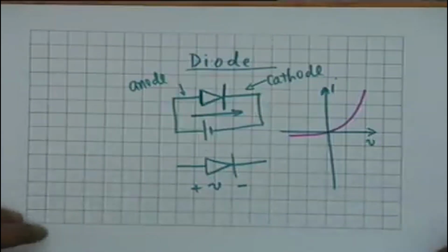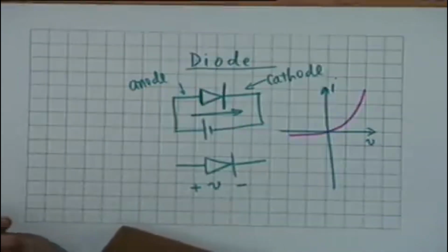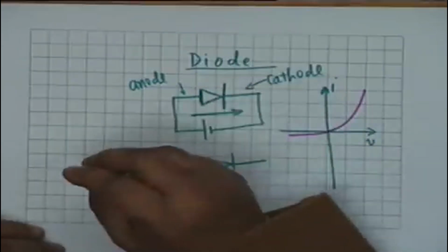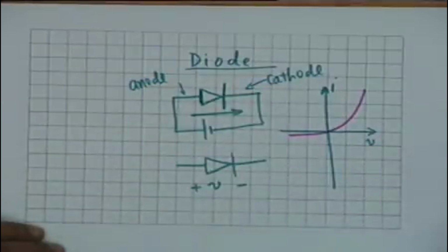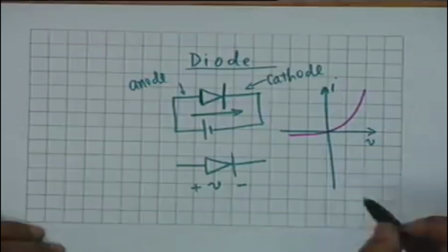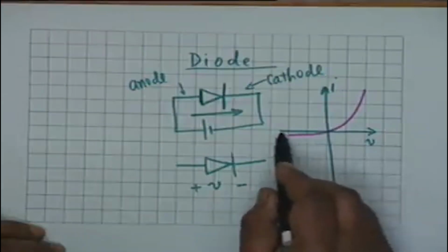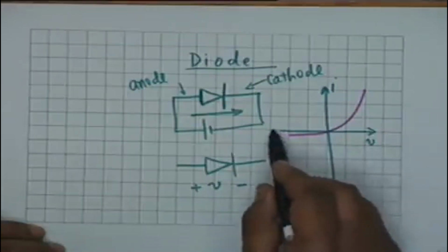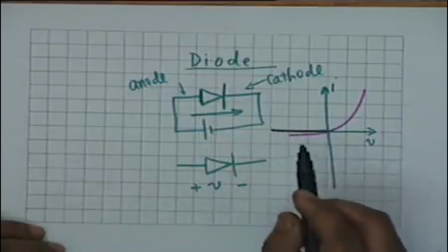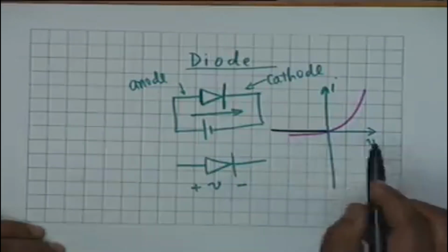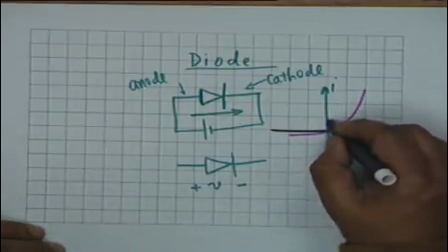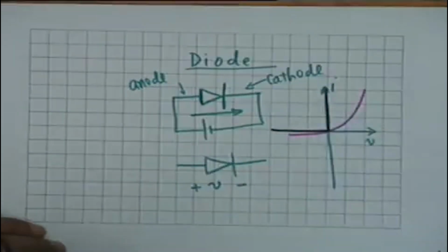All right. Now, exactly like an op-amp, we would like to idealize a diode. The ideal characteristic of a diode, I idealize it by saying that the reverse current is 0. So the ideal characteristic is that it remains 0 like this, and when V is positive, the current increases without bounds.